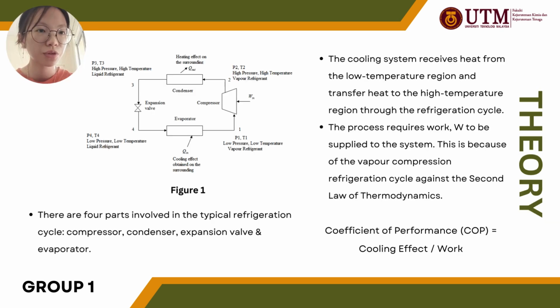I will present about the theory for this experiment. There are four parts involved in the typical refrigeration cycle, which are the compressor, condenser, expansion valve, and also the evaporator. In this experiment, the cooling system receives heat from the low temperature region and transfers it to the high temperature region through the refrigeration cycle. The process requires work W to be supplied to the system.